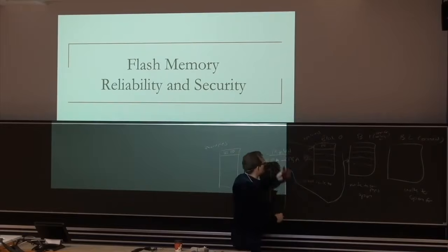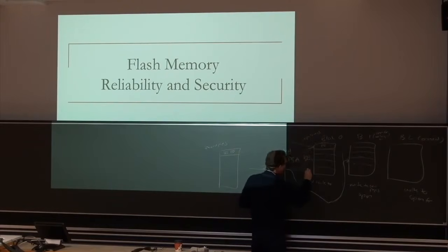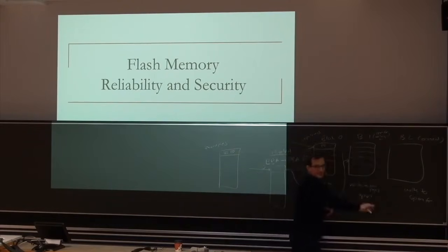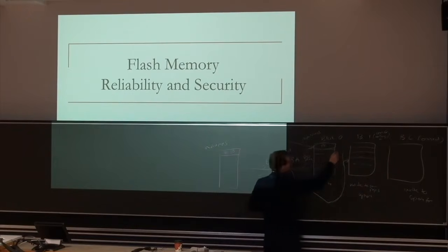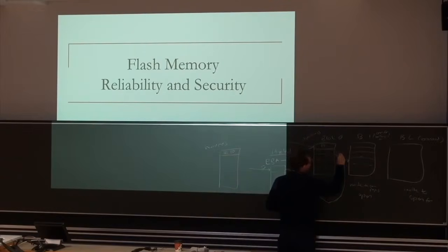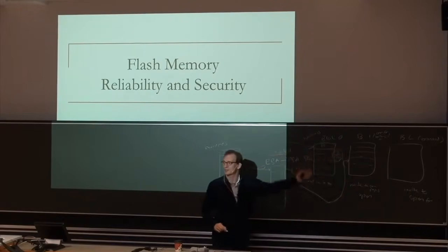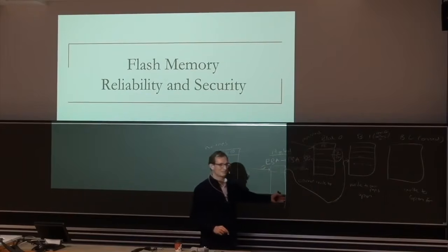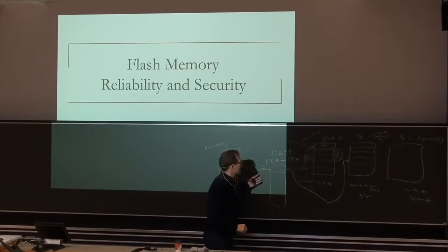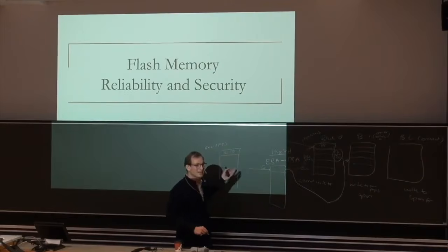And let's assume that you've written 200 of them somewhere else, because you're writing to those blocks. You've changed their mappings. Now you have only 56 valid pages here, right? Meaning that you're really wasting most of your block right now. So what should the controller do right now?